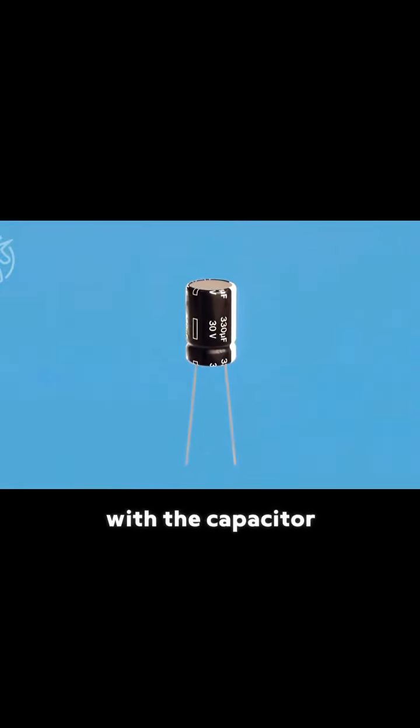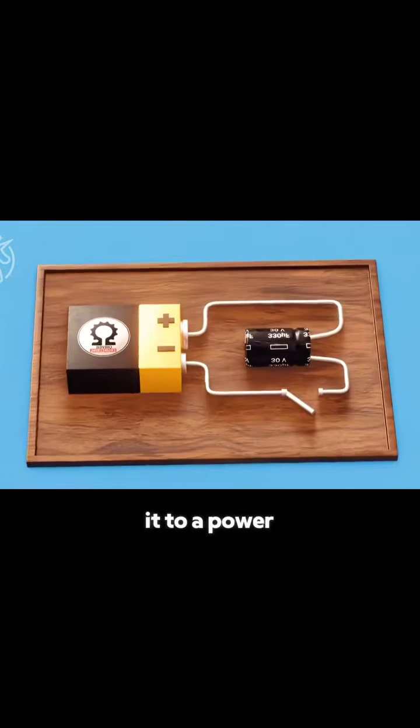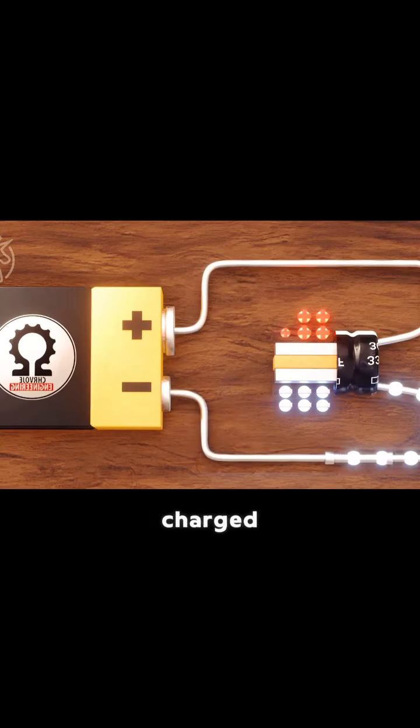Let's start with the capacitor. Its structure is actually simple. Two metal plates separated by an insulator. When you connect it to a power source and close the switch, electrons flow from the negative terminal toward the positive one. But since the insulator breaks the circuit, electrons start accumulating on one plate. The other plate, under the influence of the electric field, loses electrons, becoming positively charged. And just like that, a potential difference is formed between the two plates.